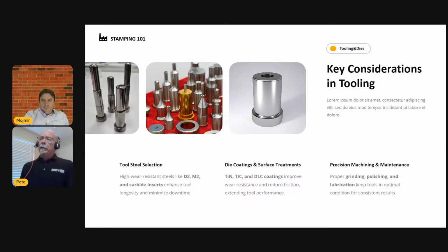So for deep drawing, and let's say you've got an irregular shape. Oftentimes when we have fracturing or galling that occurs, a lot of times it happens in the corners, right? You look at a deep drawn rectangular shell and the corners look really shiny, right?